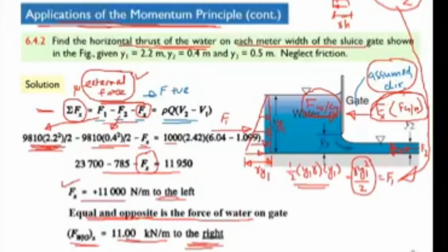But for this force that you calculate, we have to consider these forces here, F1 and F2. Clear? Because these are the hydrostatic forces, and you have to consider them, because if you do not consider these forces, how can you accurately calculate this force? Because there is an effect of these forces here. You want to calculate this Fx. So Fx will be equal to this minus this rate of change of momentum.